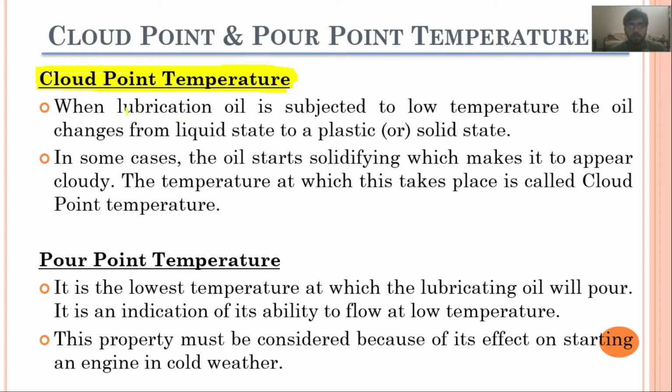So when the lubricating oil is subjected to low temperatures, the oil changes from liquid state to solid state, and in some cases the oil starts solidifying, which makes it appear cloudy. The temperature at which this takes place is called the cloud point temperature.